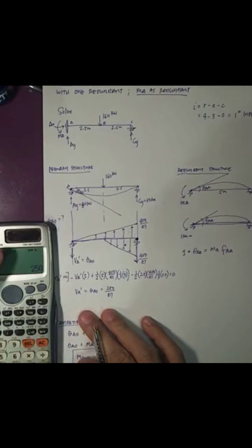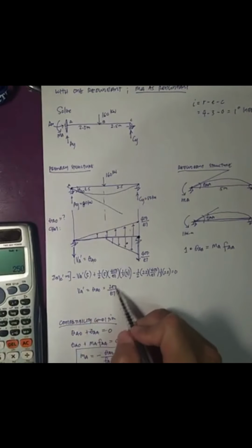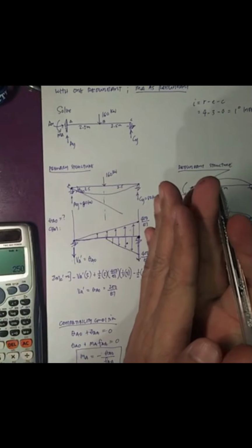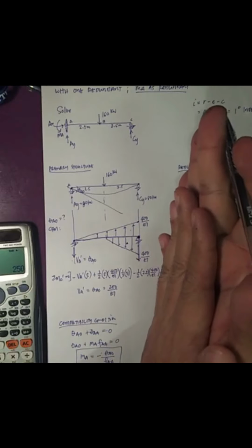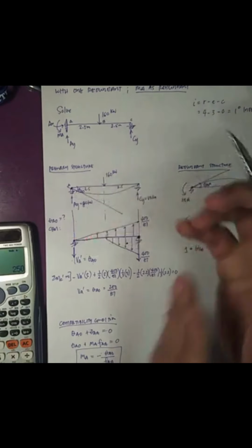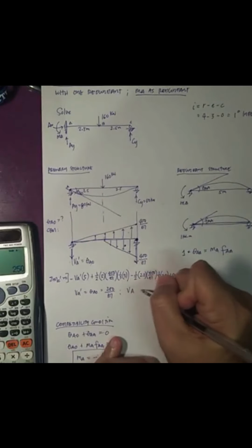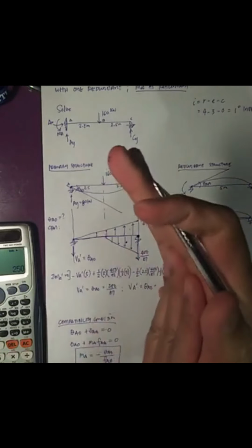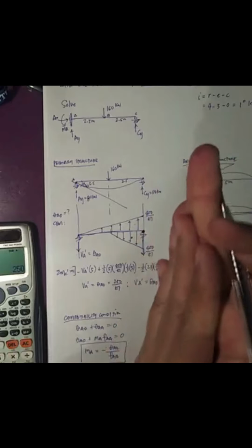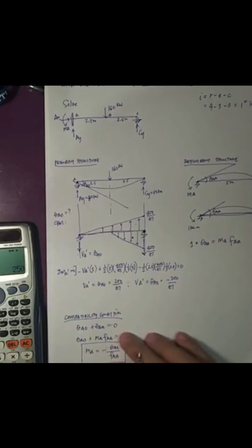Okay. So positive 250 over EI, that means that the direction here of VA is downward. So if we consider it in this sign convention, VA is downward. This is the direction of the shear. And as you can see, the true sign of shear is counterclockwise. So therefore, I could say that theta AO is equal to counterclockwise. So that means negative 250 over EI. So negative shear.